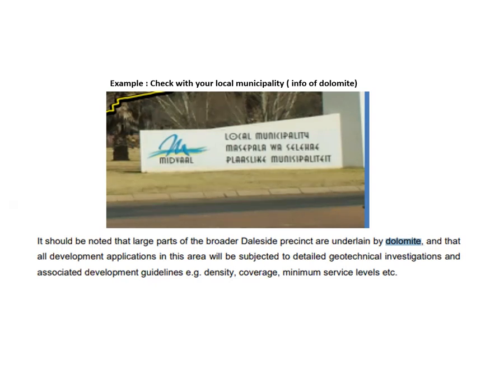You'll find that sometimes when you engage with them, they have geotechnical reports and investigations they may be able to share with you, records. They might even be able to say that for that property, the classification is D1, D2, D3. I know that Midville themselves have sent me a nice brochure of the area, and they also cover the topic of dolomite and what to consider, the good practices, and the preventative measures, which is very nice and useful.